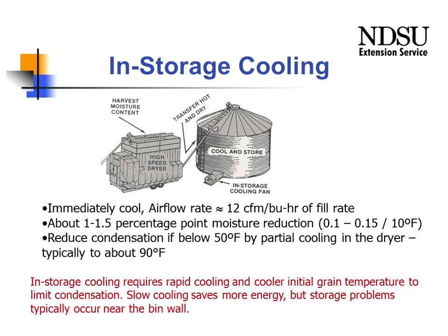If you look back at some of the early work that was done on in-storage cooling, they did not recommend that we use in-storage cooling when outside temperatures were below 50 degrees. For a lot of the corn country today, we do a lot of drying and cooling at temperatures below 50 degrees. For those areas, I think it becomes critical that we do partial